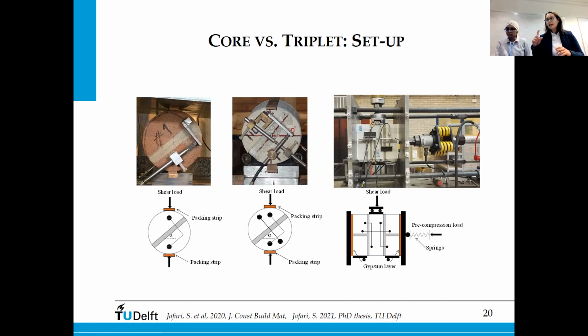We are usually within a deviation of about 0.2% of the applied pre-compression given in the standard, and we may deviate just slightly when we reach the peak strength. But with the system, we can generally stay quite constant with the pre-compression load that we apply.